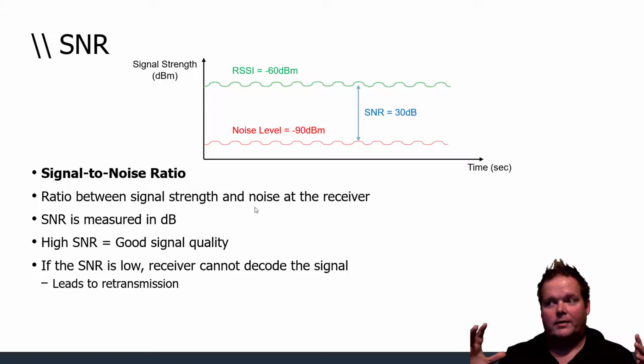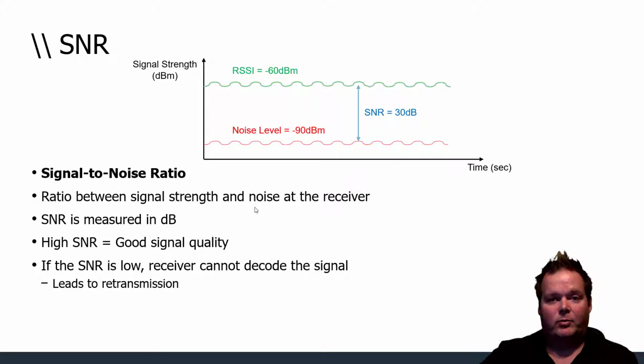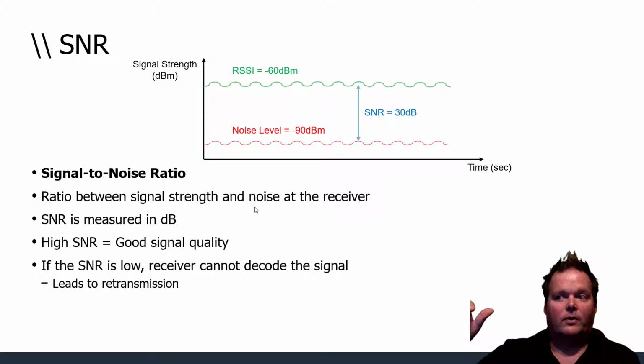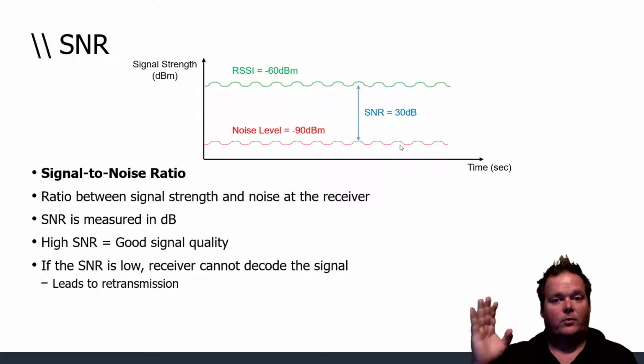So what are we doing again? We want to figure out, let's say our design requirement initially required 25 dB separation between usable RSSI and the noise floor. Let's say we've got an RSSI of -60, for example, and a noise floor of -90. That's a 30 dB SNR. Well, what if we had, let's say, a -75 RSSI? It could go that way, or the noise floor could be higher. Either one, if I'm not getting what I'm supposed to be getting, there's a reason. But especially if that noise floor is higher, or if there's something going on with that channel, with that frequency.